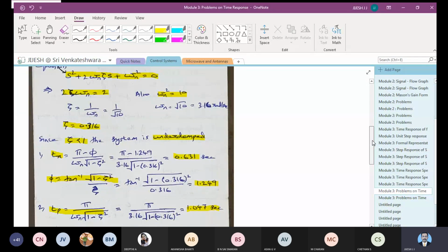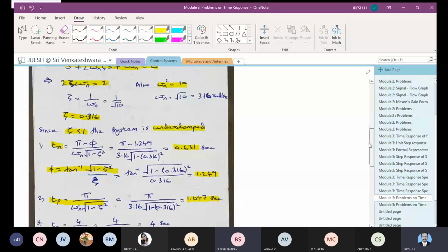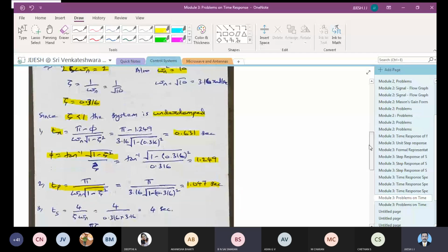It's very easy. What is the settling time answer? 3.998 seconds. Yeah, that's 4 seconds. Fine, correct. So next we'll see maximum overshoot. But before that, we have to see this TS is 4 divided by zeta omega n. You have to use this equation.